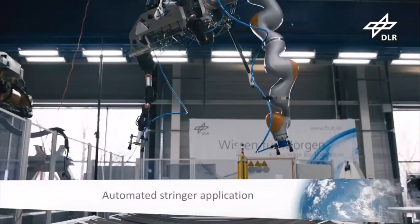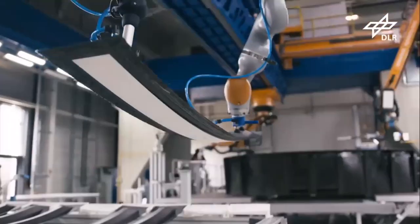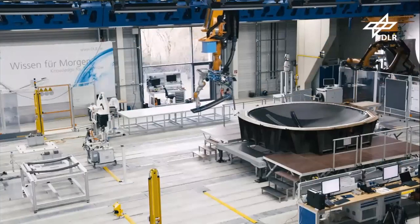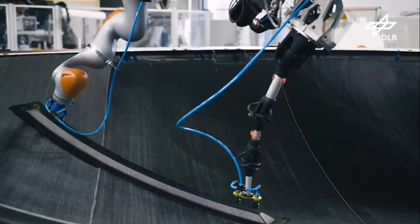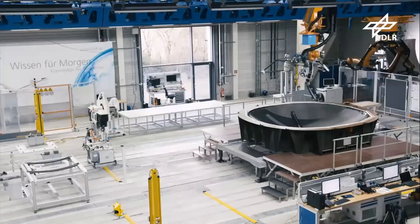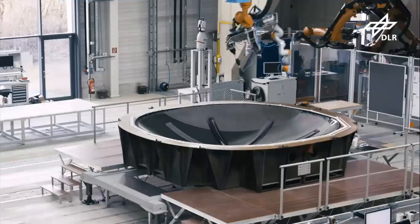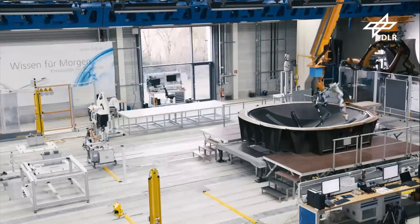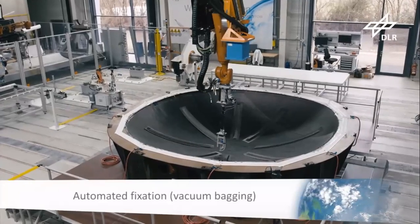The in-house developed multi-kinematic gripper picks stringers as stiffening elements automatically, and after reorientation during the transfer places them on the preform in the exact position. Vacuum grippers on the freely configurable manipulator arms ensure reliable holding of the stringer. They have to be positioned differently for every stringer, which allows bringing all of the 8 stringers from the pickup station to the preform. For the fixation of the auxiliary material packages, the epoxy resin is applied.